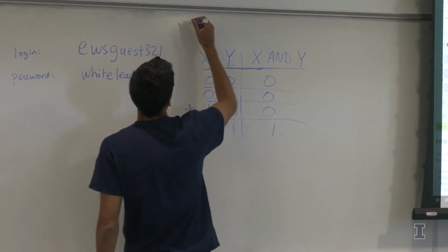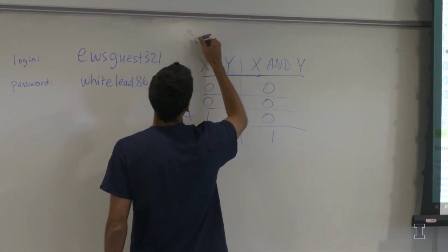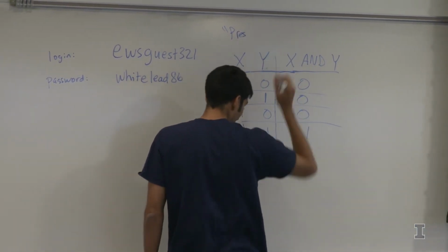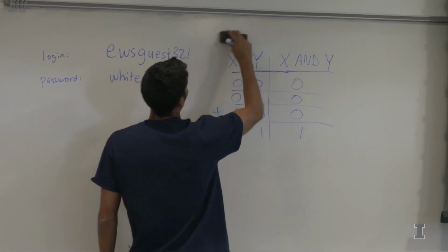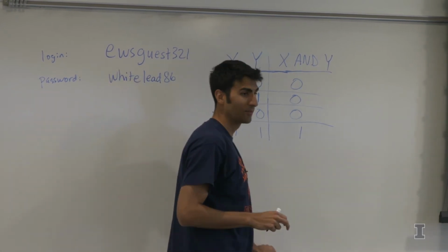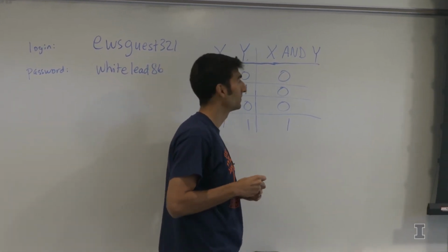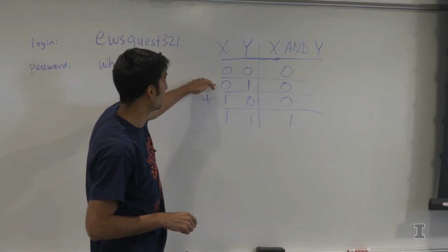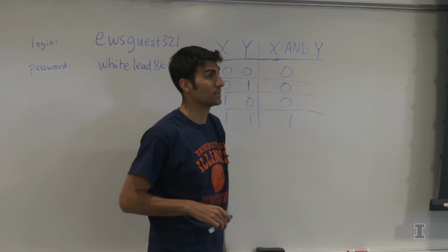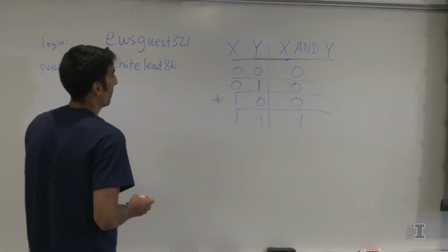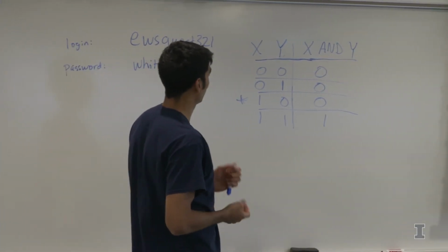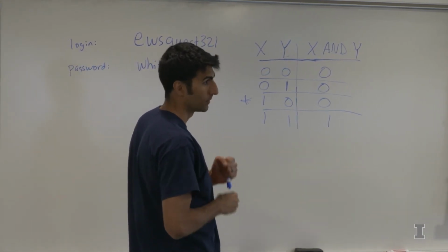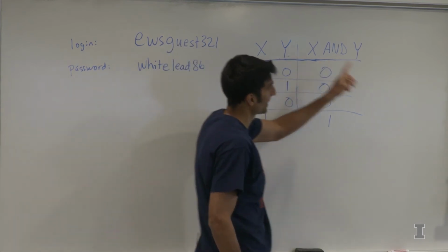So maybe it would help if we wrote a table here. Pressed. Now I'm going to draw a little picture real quick. If you only toggle the bottom one and not the top one, it'll also stay off, right? Right, and that would correspond to this row here. It's an AND. It's got to be the X and the Y, both conditions have to be met in order for it to come on? Yep, it sounds like it. That's what this AND gate is doing.